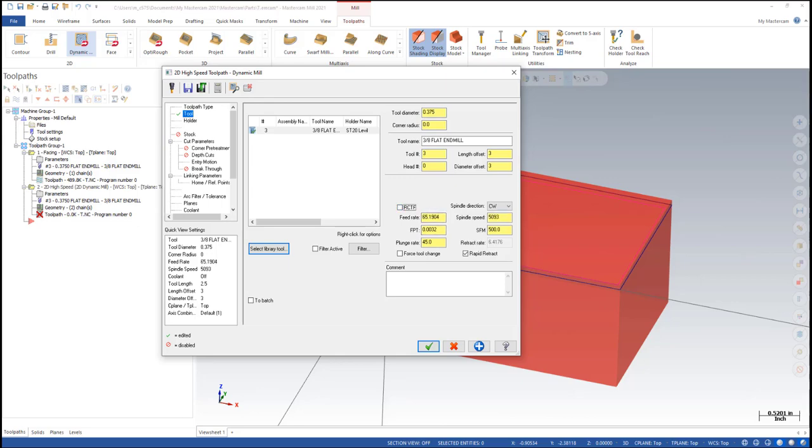And if you notice, it did change the feed rate some, and that value is dependent on your specified radial step over. It just converts the feed rate to give you your actual commanded chip load, because anything less than 50% radial, you're going to have something that is less than commanded due to radial chip thinning if you're climb milling.